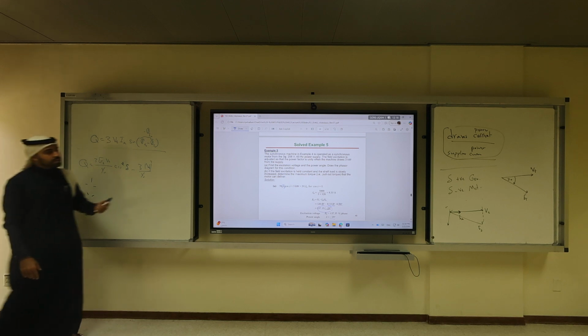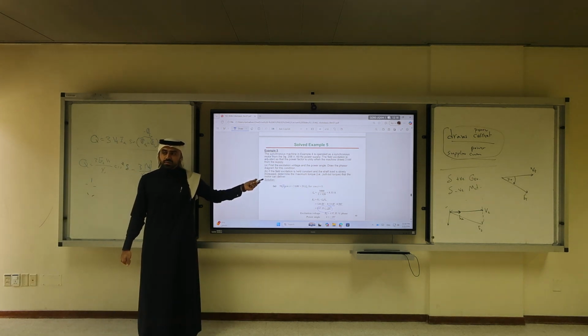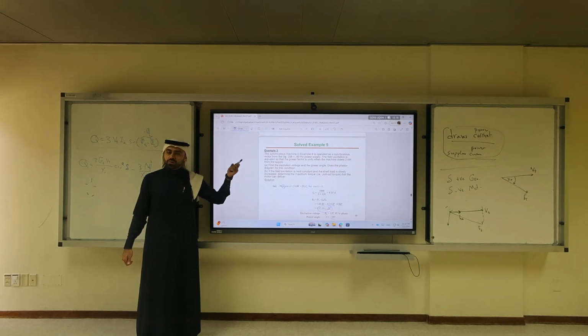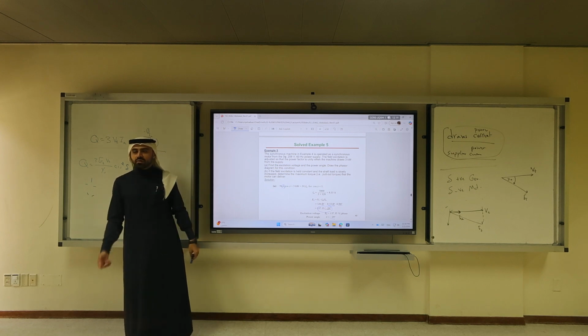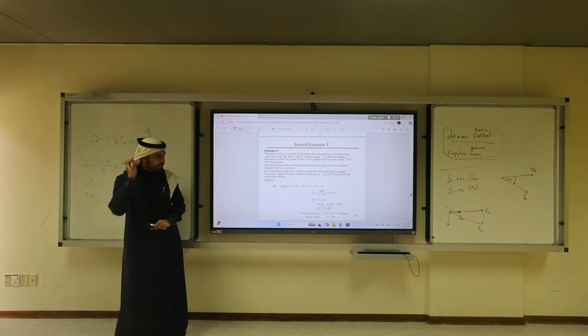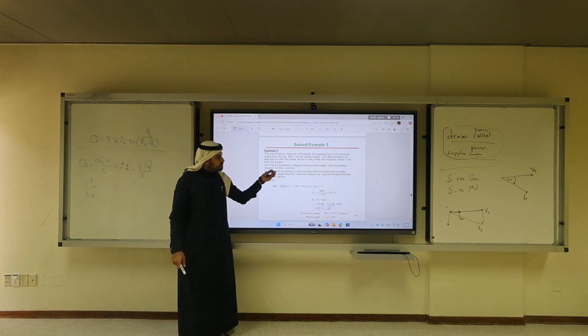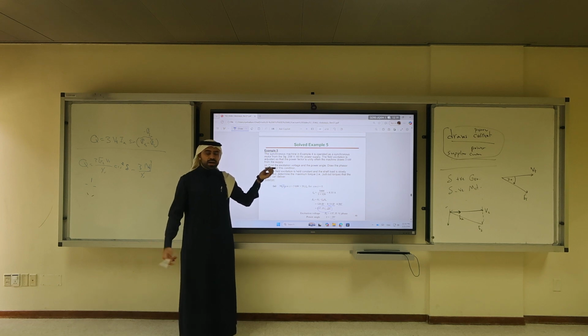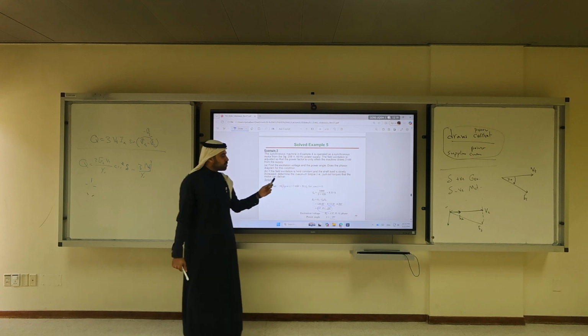So this problem is applicable for EVs. You cannot change the excitation for a synchronous motor. The only thing that you can change is the voltage, and you just control the voltage, the current and the frequency. Variable speed drive, power electronics, okay? So the case of constant field excitation is realistic in permanent magnet synchronous motor. So now we're experiencing a higher torque than usual.